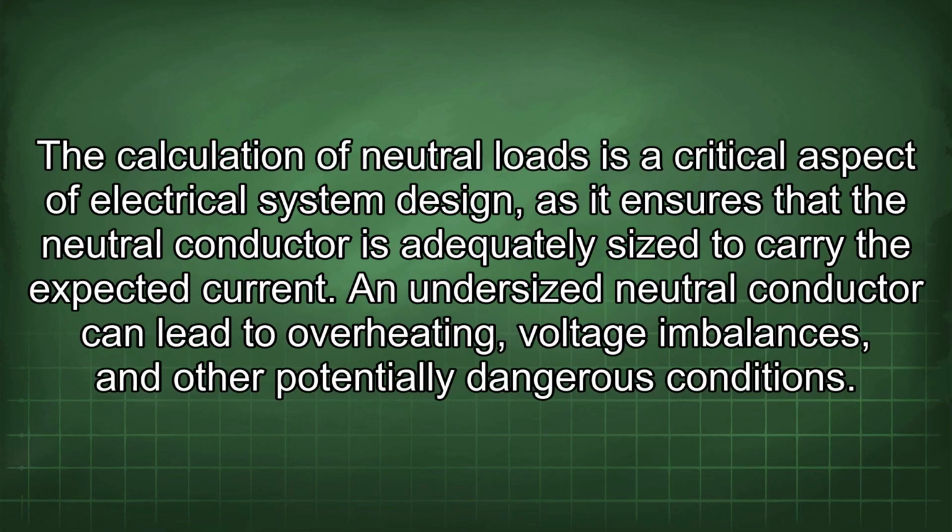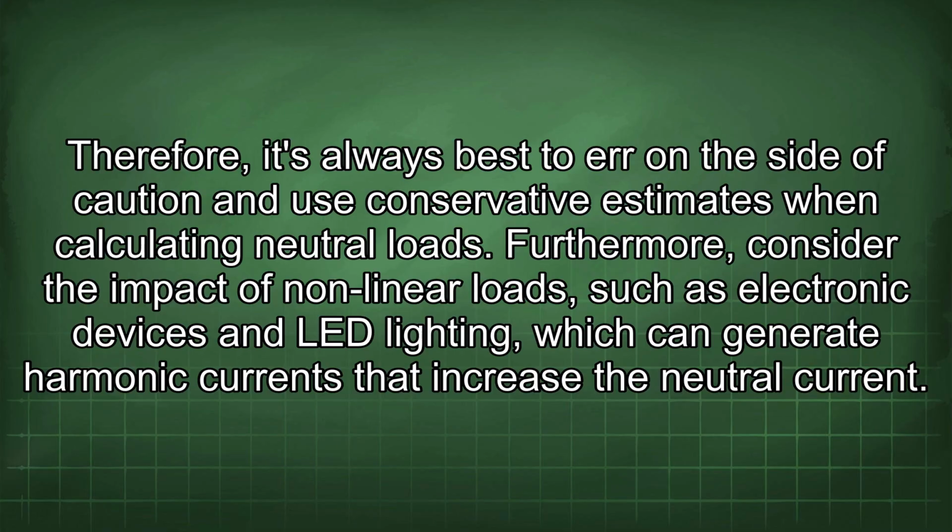The calculation of neutral loads is a critical aspect of electrical system design, as it ensures that the neutral conductor is adequately sized to carry the expected current. An undersized neutral conductor can lead to overheating, voltage imbalances, and other potentially dangerous conditions. Therefore, it's always best to err on the side of caution and use conservative estimates when calculating neutral loads.